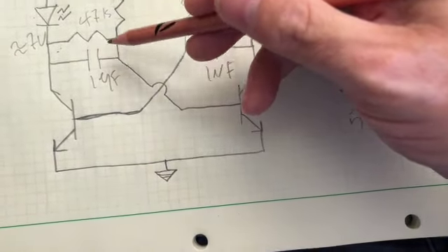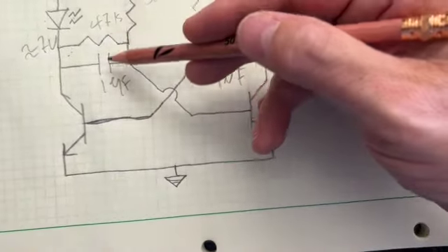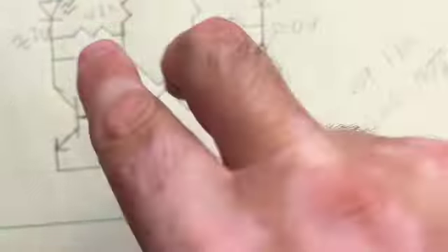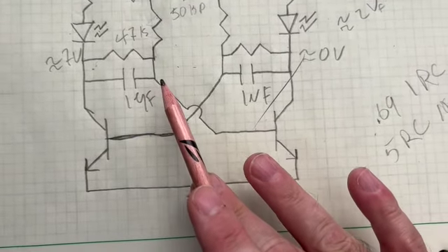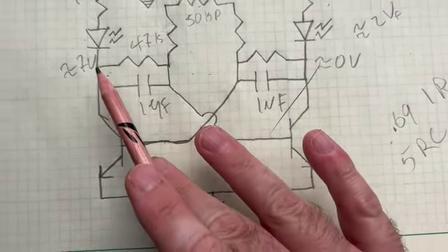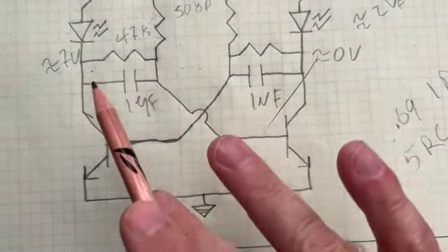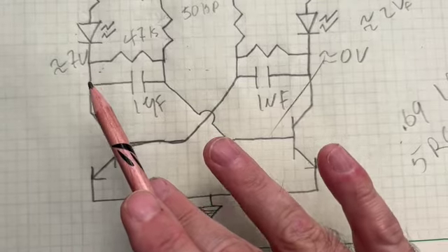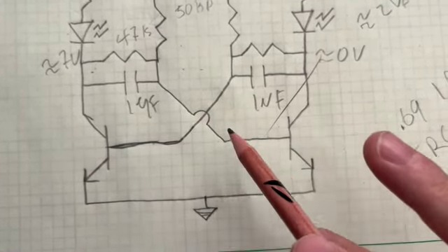Capacitor reaches charge, turns on the other LED, which drops the voltage down, turns off this capacitor because this becomes negative voltage on this side, the 0, and the voltage essentially flips, right? So as you see here, there's 7 on this side and essentially 0 on this side. When this turns on, this becomes 0. Well, the capacitor still got the charge. It's just now that this is 0 in reference to ground, this becomes negative in reference to ground.